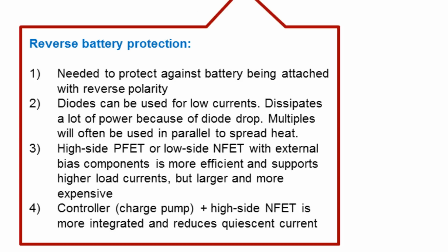So what is the solution? The solution is to use a charge pump controller with a high side NFET, N-channel FET, which will provide a more integrated solution and will also reduce quiescent current.